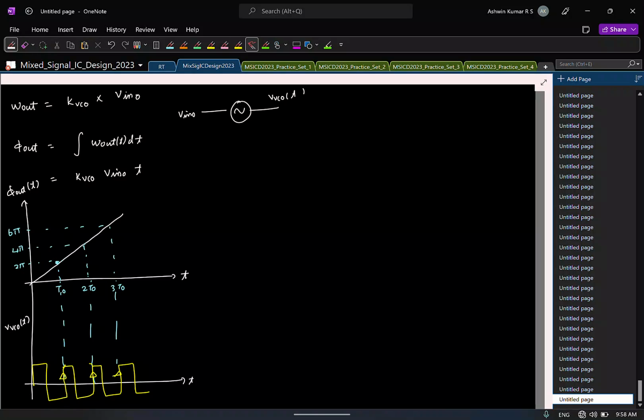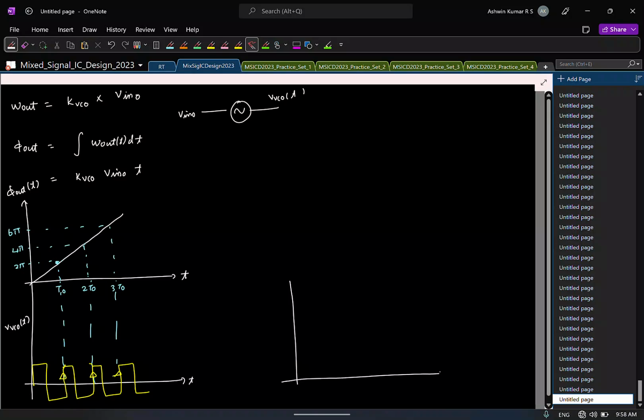And for that I'll take you down to this notion of quantizing voltage. So let us say I have an incoming voltage signal and I want to quantize the voltage. For quantizing the voltage, I take the incoming voltage and compare it with a bunch of reference voltages.